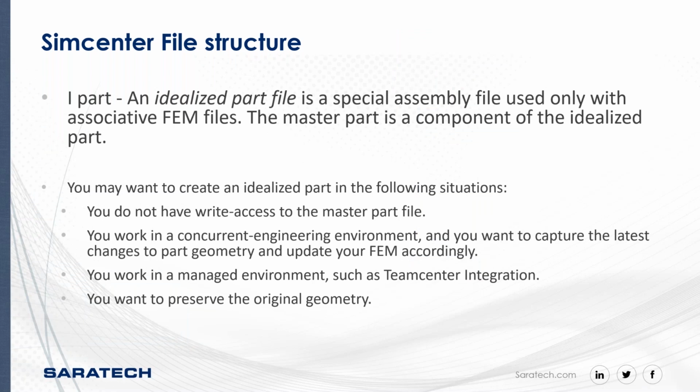The idealized part is a local, I'll just say CAE part that you are going to use. Now, why would you create this idealized part? Well, maybe somebody else is working on the same part with you. If you remove a round or a fillet, or you extend something, or delete something, you're actually editing that part. So what we'll do is create an idealized part, which is just an associative copy of it, and we can make any changes that we want, and we don't edit the actual part.